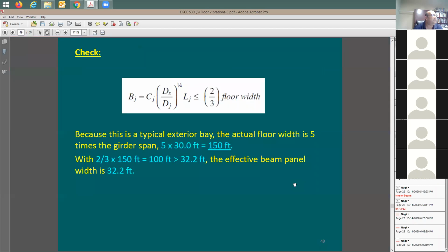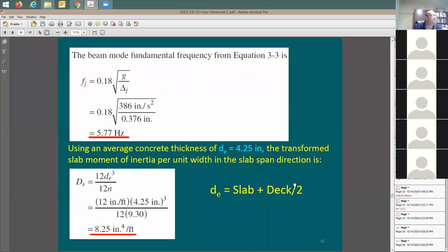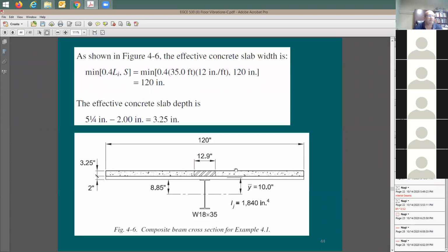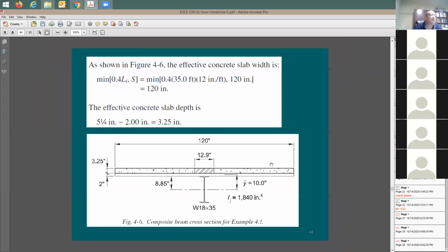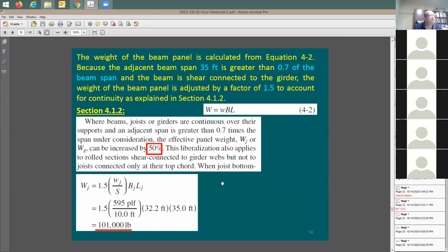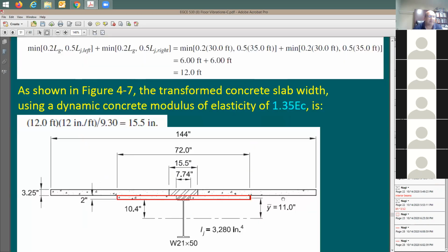So let me take you back to this beam analysis. So in the beam analysis, I have the deck running right and left. And I don't have any concrete flutes here that stick down. While in the girder analysis, if I may move here forward, I'm gonna have some flutes that stick down below here, like some webs and stuff like this.